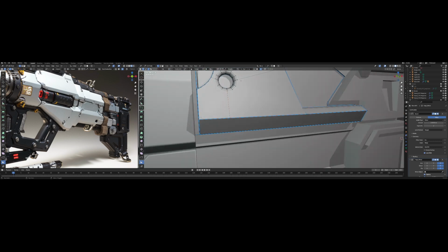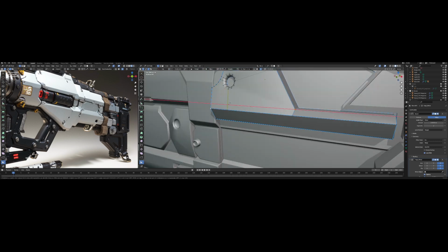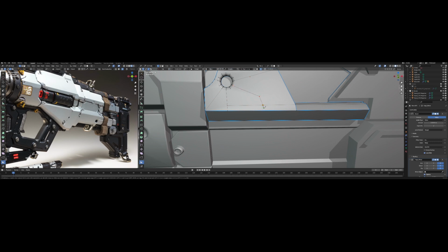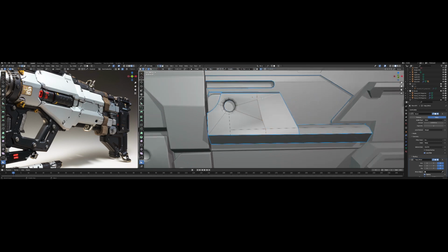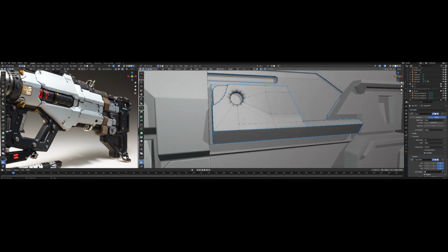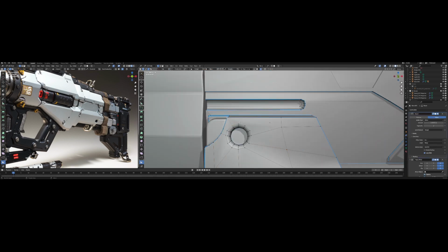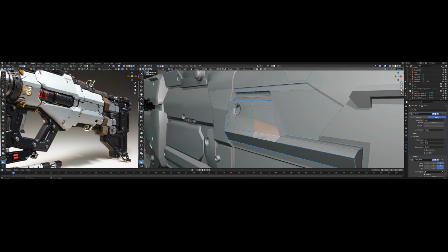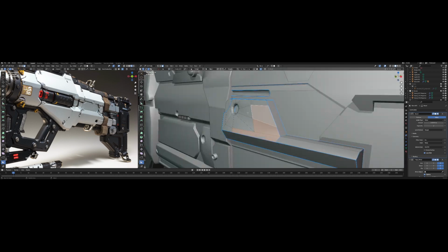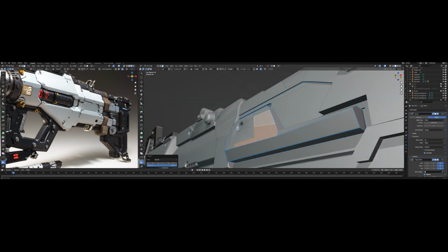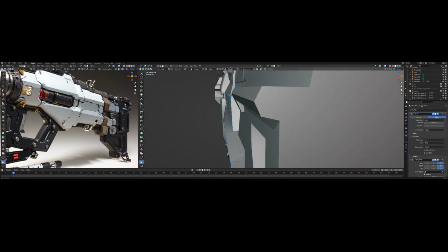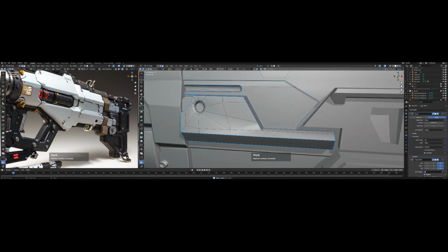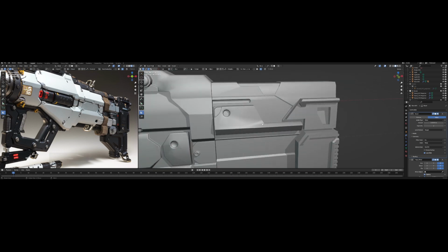But another step I have to mention: if we directly use the clean mesh, there are some steps to note. Actually, I think it is better to not fix all of its geometry or shading problems first, and then press the clean mesh. All those extra lines and geometries that we added on those meshes will be removed by these functions, and the shading problems will not be solved.